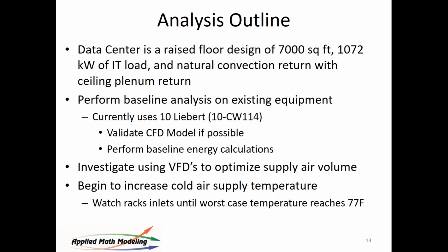In other words, you want it to reflect the real world situation as much as you can without getting so carried away that the model becomes too complex, the time to compute it gets too long, and it gets too big to handle. You want to perform some baseline energy calculations. And then in this study, we're going to take a look at using VFD to optimize airflow volumes. In CoolSim 4.6, the new release, we have an ability to do that in the model, and it will predict for you the energy delta associated with the change. That's what we're going to show you today. We're going to look at the rack inlets, and we're going to optimize the case until we get to about 77F. And then we're going to stop and see how it looks.